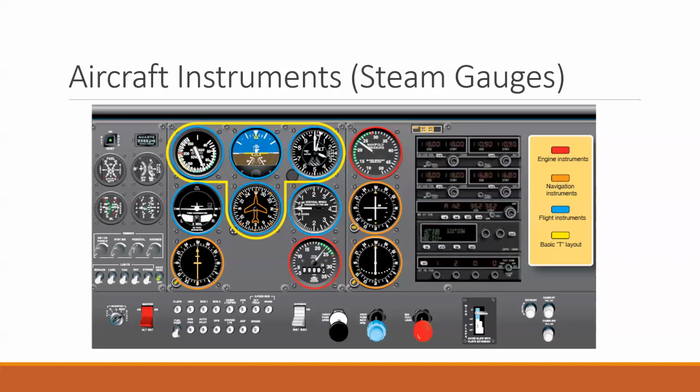And you can adjust this based on where you're at. It has a little window on the side that you can turn a dial, and you can adjust it to your current pressure so that it knows what the pressure is outside to give you a better reading of what the actual altitude is. So for instance, if your pressure was 30.01 inches of mercury, you dial in 30.01, and it would calculate the proper altitude based on your pressure.